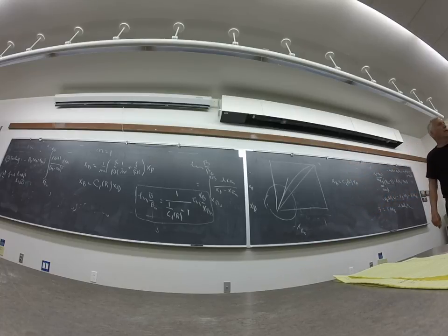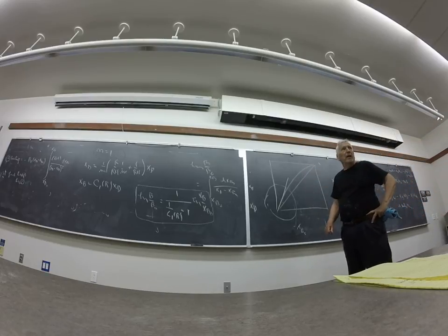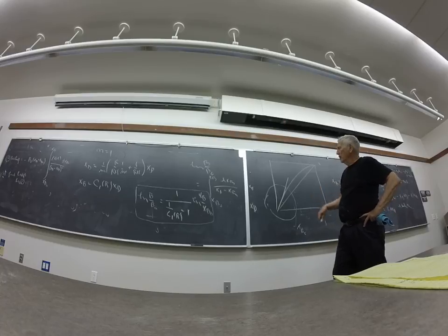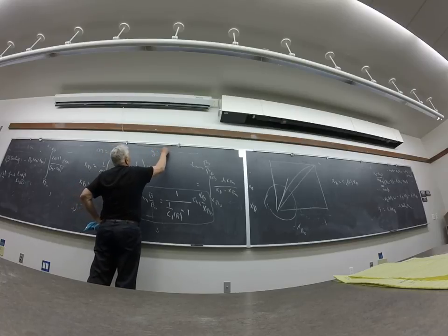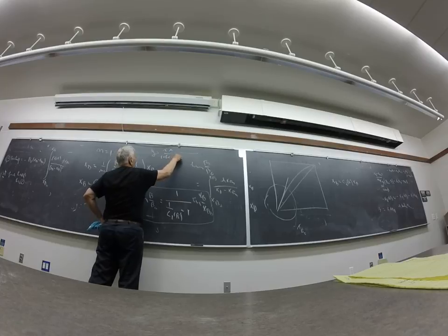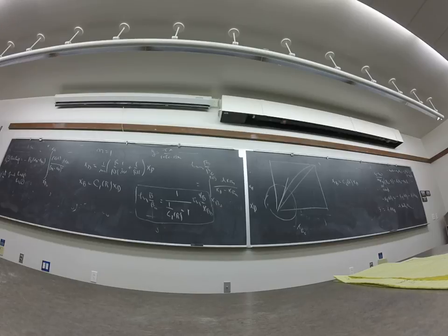It's the slope of the equilibrium curve at x1 equals 0. It's a distribution ratio. So when things are dilute, they're not complicated. I haven't even got the curvature of this thing into the game yet. But you can look at here, do this. Write y equals alpha x over 1 plus (alpha minus 1)x. That's true whether alpha is constant or not. It's just that if alpha is not constant, you can't make much use of it.